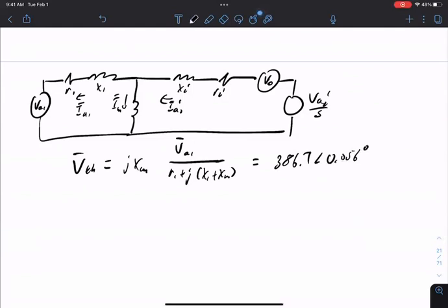When you compute the Thevenin equivalent, mostly this shunt is not going to matter too much. So this angle will be small, and this number will be very close to 690 divided by root 3. That's just a sanity check to see if you've done the equations correctly.